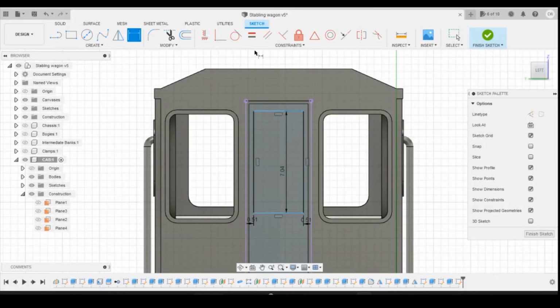And it says on the diagram that this corner is the same height as this. So first of all, what I'll do is I'll add the fillets in, and we're doing those at 0.5, and then we're going to horizontally constrain that point to that point. Okay, then